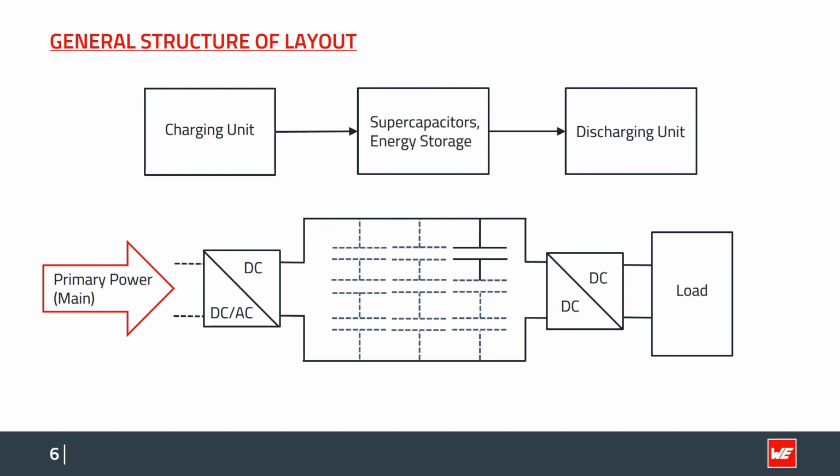The supercaps do not require time and voltage control charging like a battery. The charging unit needs, however, to be able to handle capacitive loads and charge the capacitor safely at the desired constant current. All it needs is a current source.